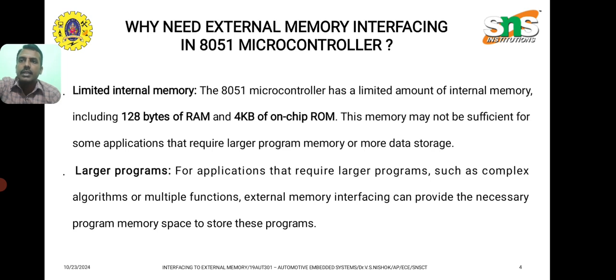Why do we need external memory interfacing in 8051 microcontroller? So here are some points. The main reason for the interfacing between the external memory and the 8051 microcontroller is, first, limited internal memory. 8051 has a limited amount of internal memory including 128 bytes of RAM and 4 kilobytes of on-chip memory. So this memory is not sufficient. So that is the main reason.